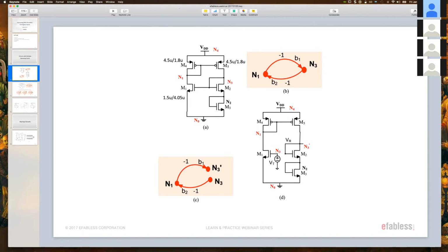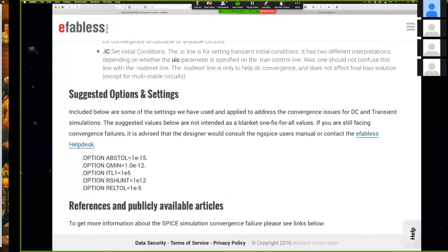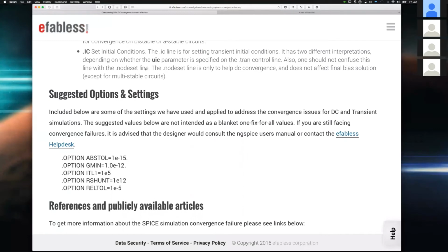Based on what you just explained, let's say I figure out a set of values for the tolerances and do a .dc, and it works, but the same values don't work when I do a .dc with the temperature sweep. So do you have some suggestion to get a .dc with the temperature sweep working compared to just a simple .dc?